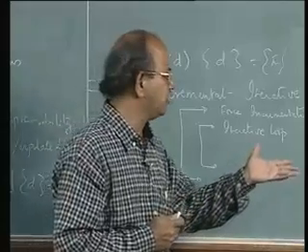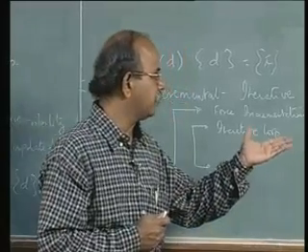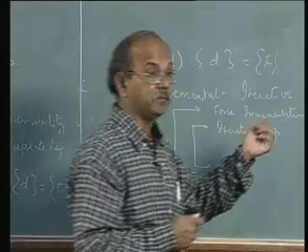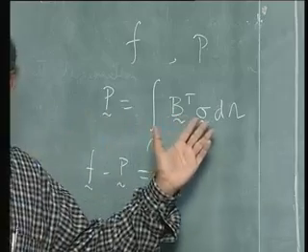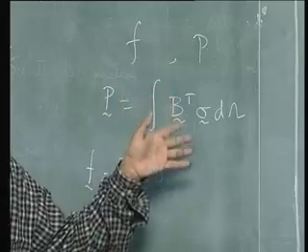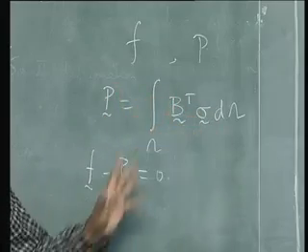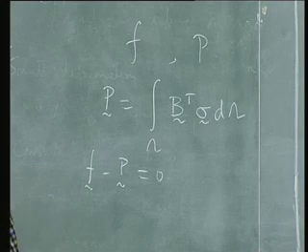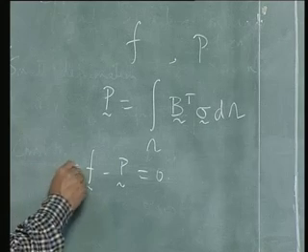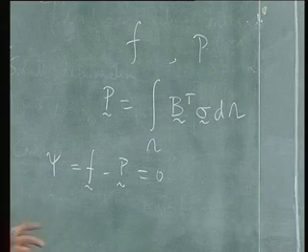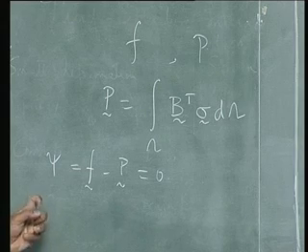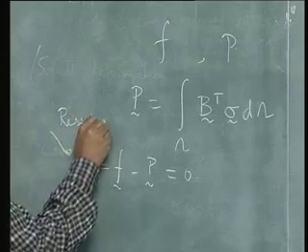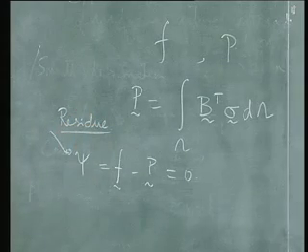As I had already told you, it is not possible for me to get that internal force straight away, because sigma now is not just D epsilon; that D itself is a function of epsilon and so on. So I can't write it like K, like what I had done at that point of time. So I will definitely end up with an error or residue. This is what we call residue.